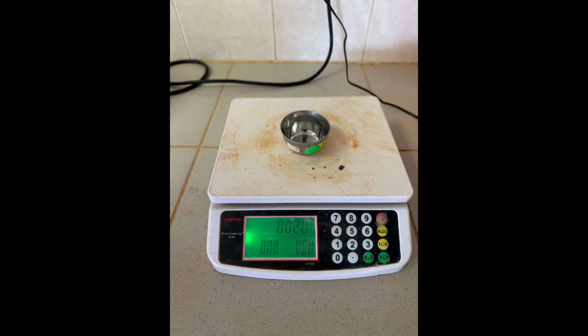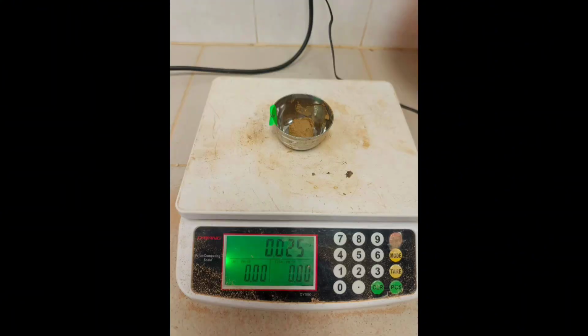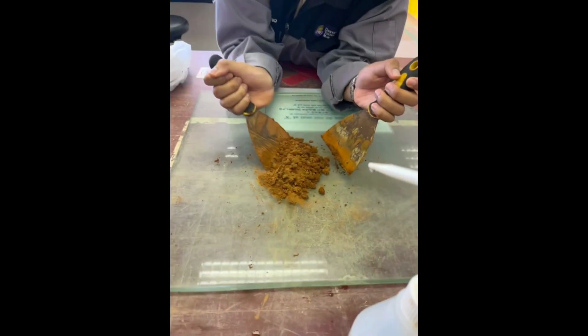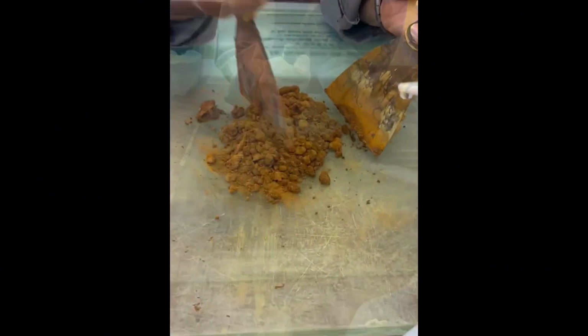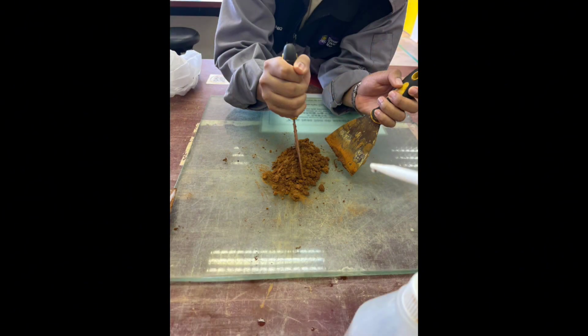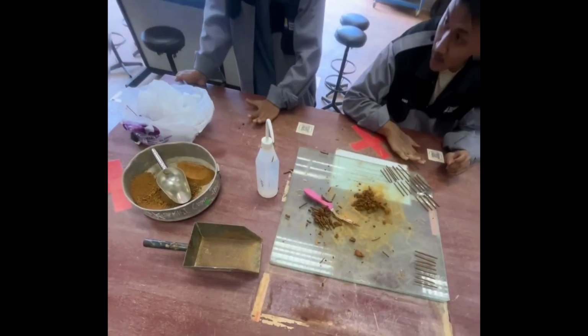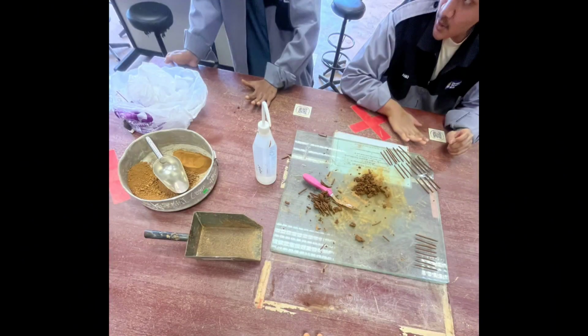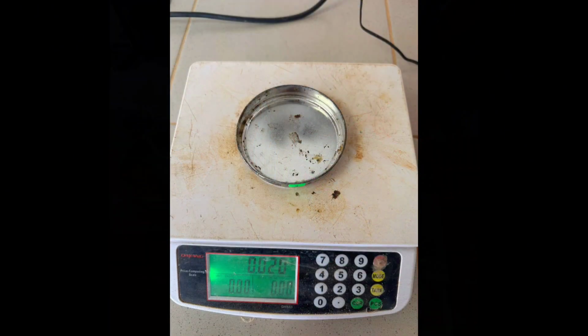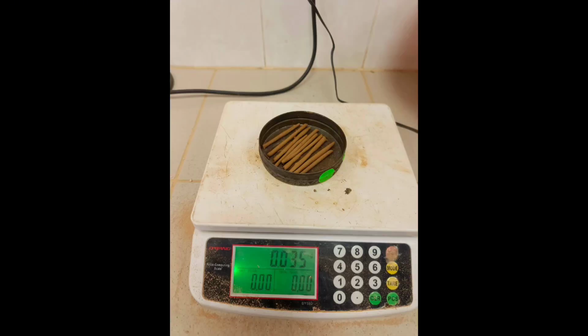The cone was cleaned and 2 additional penetration readings were taken, with the difference between readings kept below 0.5 mm. A moisture content sample of about 10 grams was collected from the penetrated area. The procedure was repeated at least 2 more times using different moisture content. The remaining 20 grams of soil was mixed with distilled water until it reached a rollable consistency.